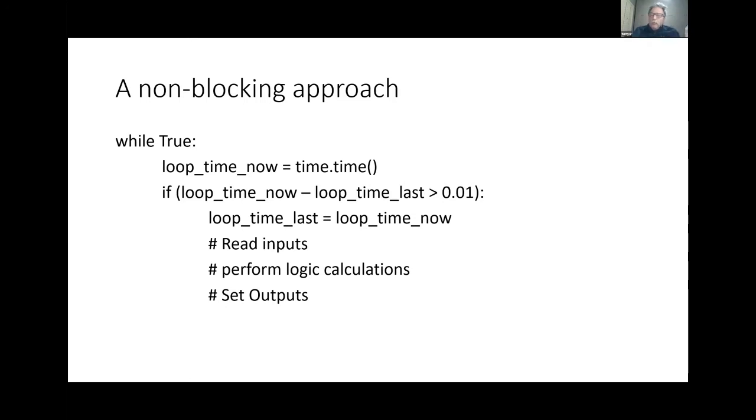So this idea of reading eight inputs in one instruction fits into this logic too. I just read each card here. Each card's got 8 inputs. So if I've got 3 cards, I just do 3 read instructions, perform all the calculations, and then do 3 write instructions.